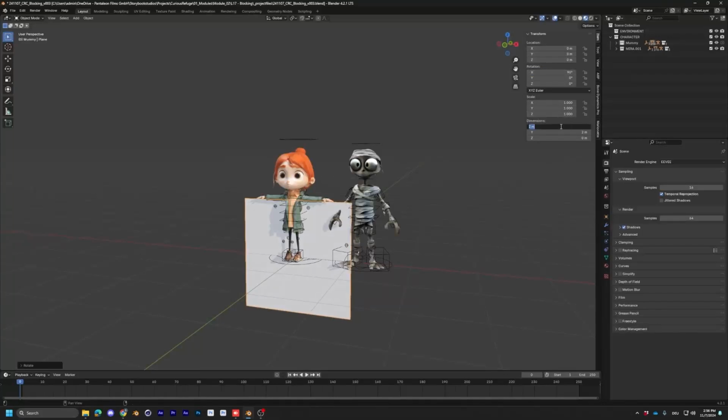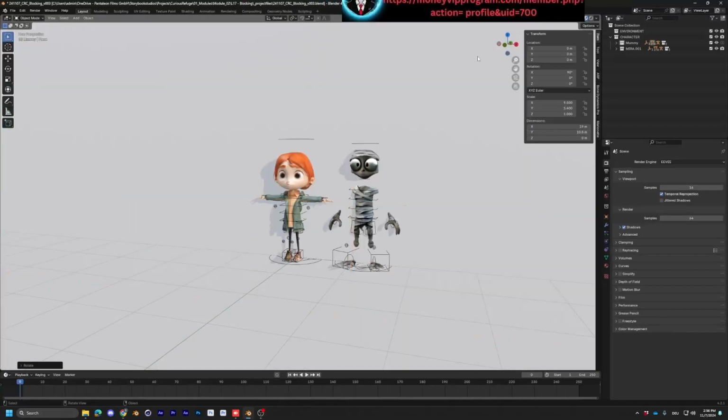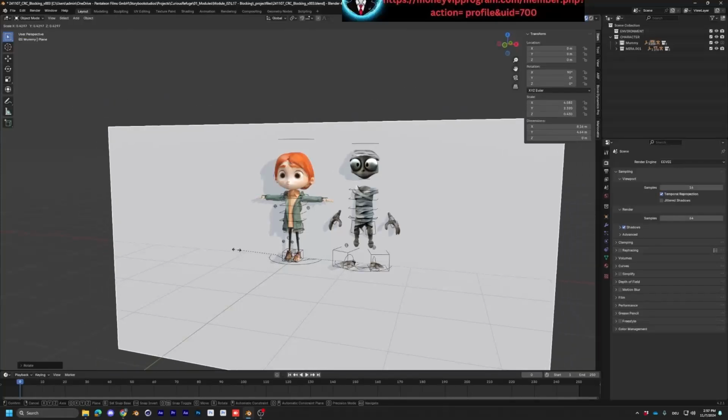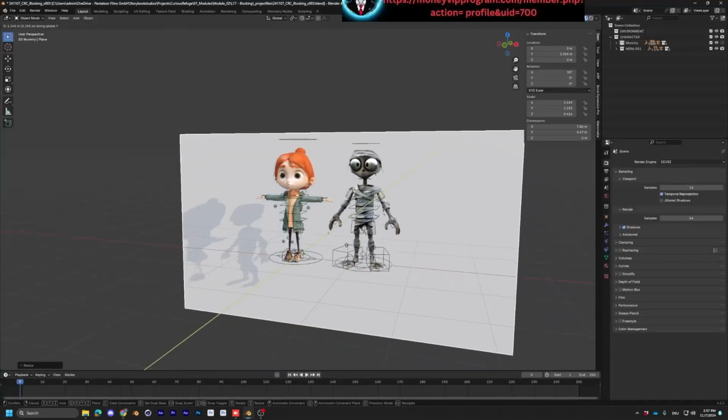And we want to adjust the scale to a 16:9 ratio and put the scale a little bit down by pressing S. And this will be a placeholder for our environment. So move it a little bit back by pressing G and Y. And click. And now we're going to create a material for it. So go to shading.